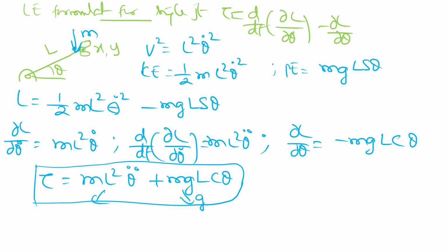So these are the equations of motion for the single link or single joint. This is using Lagrange-Euler, and the equation we derived is the equation of motion. Here there is no Coriolis effect because your link one alone is rotating, it is not rotating with a second link. Okay, so this is the basic equations of motion. So now let us discuss forward dynamics and inverse dynamics.